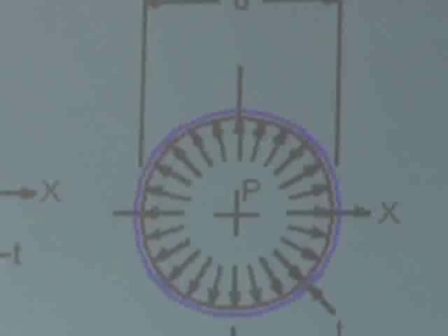These pressure vessels that we talked about, that was probably 2 lectures ago. We did talk about not having square ends, because when you're loading it, you will open the corners. So what we have here is an intermediate geometry that has a corner, but it's not at 90 degrees. It has some angle to it. And just to recap on this one, because it's something very important.